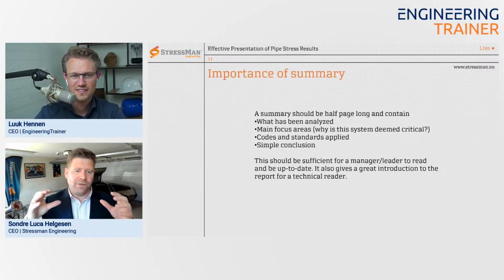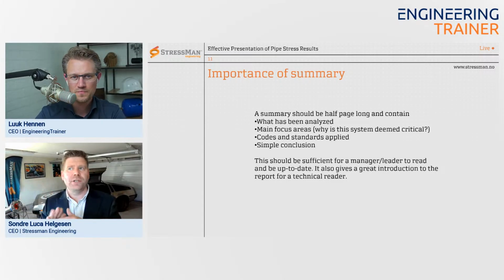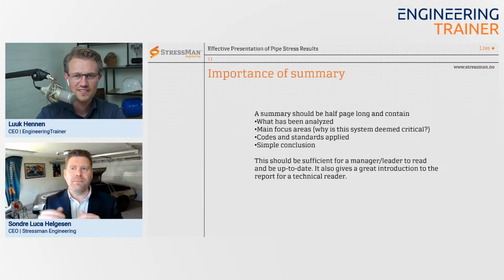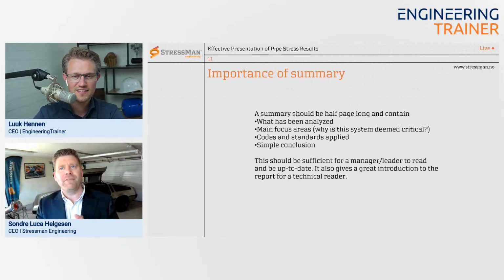So you see, okay, if you're conservative, we assume that all the expansion of this pipe is going straight up. What would happen to our pipe and the existing piping? And then we assume that the opposite thing might happen, doing some envelopes just to evaluate that what we're doing is making it better. We had that case, back to the pump discussion we just had.